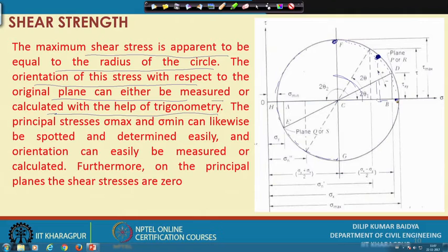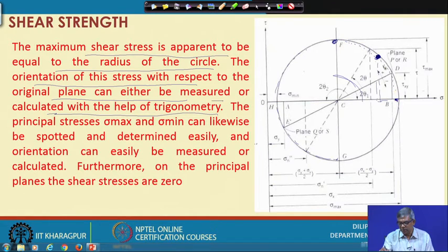The plane on which the maximum normal stress occurs, you can see here at this point shear is 0. But normal stress, if I move along this circle, is increasing like this and again decreasing. Normal stress becomes maximum here, and if I rotate then it comes to a minimum here, and then if I go this way again it comes to this point.